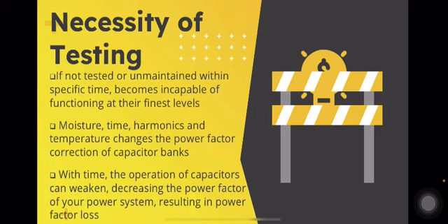Why do we need testing? Why is the testing required? Due to moisture, time, harmonics, and temperature changes, and the power factor corrections, we require power capacitor banks. Already installed power capacitor banks, if they are not tested or maintained within the specific time, become incapable of functioning at their finest levels. So, with time, the operation of power capacitors can weaken, decreasing the power factor of your power system, resulting in power factor loss.